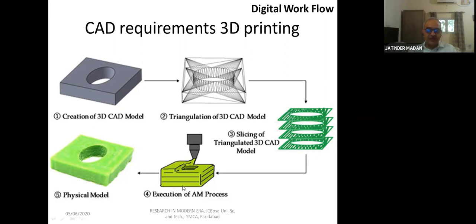For example, you have the powder layer over here for this upper layer, and you bring the laser, you throw the laser in the specified area. Those specified areas are qualified. The rest of the area where you have the powder, but you don't bring the laser for sintering, remains powder as such. You remove that powder afterwards, and this is the physical model that you will get. Of course, there will be some approximations and some errors. This is the digital workflow for 3D printing.